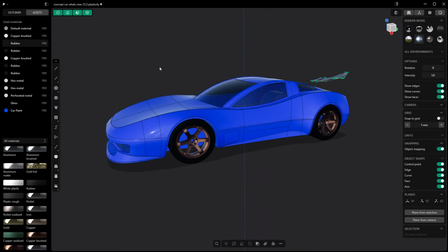And just keep in mind that some of the tools you find, things like the new Align tool, are going to be studio only tools. Anytime you see a tool that uses XNURBS as the basis for it, or in some cases, file conversions, whether import or export, some of those are going to be studio only options. But a lot of the new tools being added, things like measuring curvature and continuity, those are baked into the program at both the indie and the studio level.